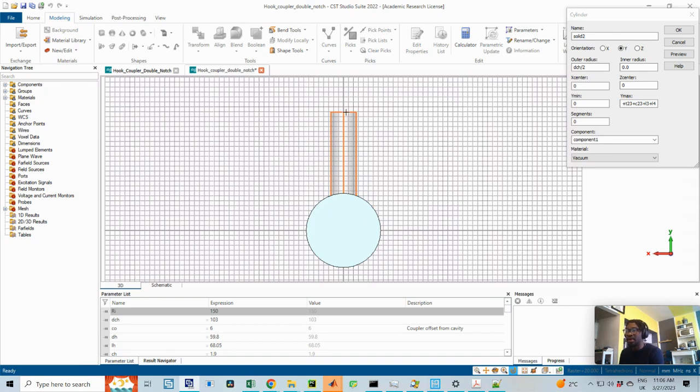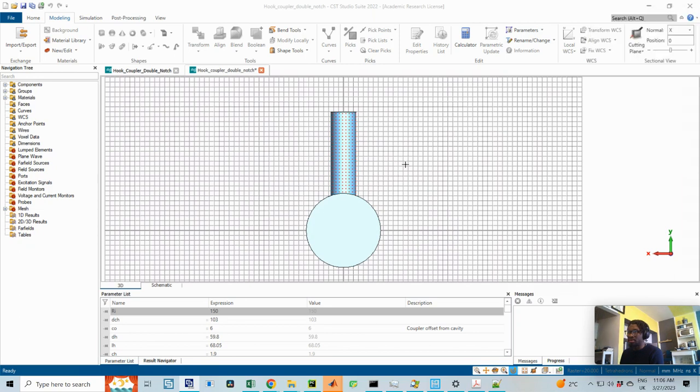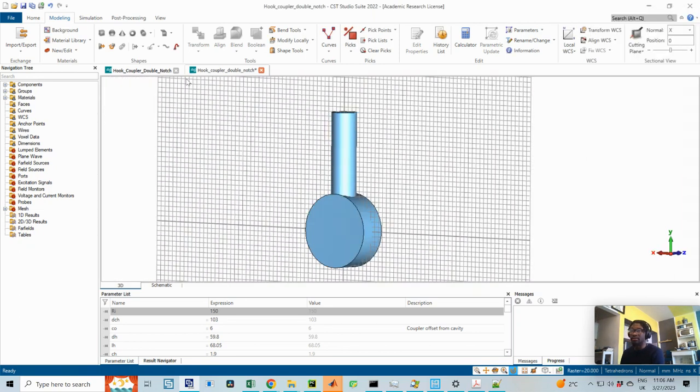So we have the first cylinder that makes up the chamber, and I could click OK. Hopefully everything is correct. Now before I click OK, I go ahead and copy the variables, the y max here, because I'm going to be building on top of it, and then when I'm modeling the antenna itself, I'm going to be removing some of these variables. So I'm going to press Control A to select all, and Control C to copy, and then OK. Now none to all, so I'm not merging anything. So this is what I have.